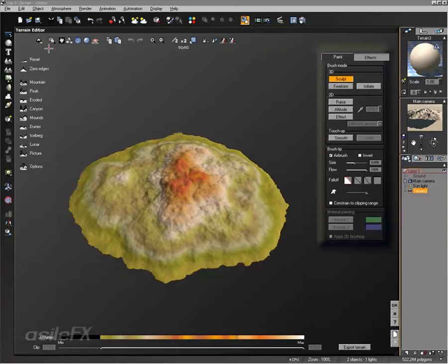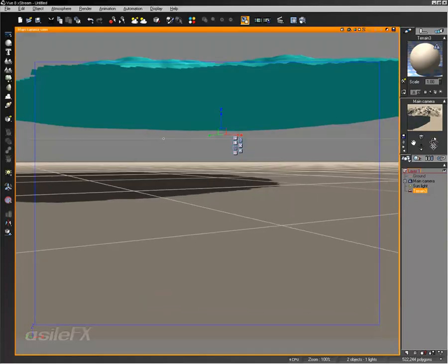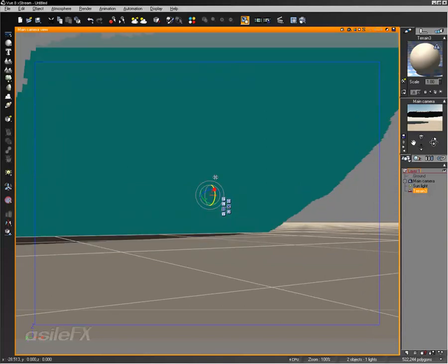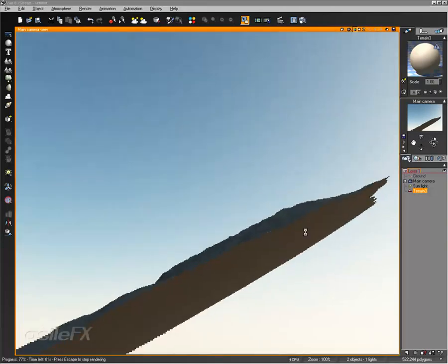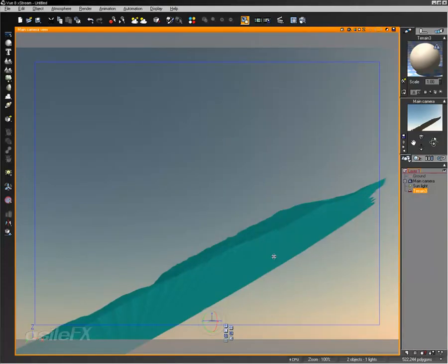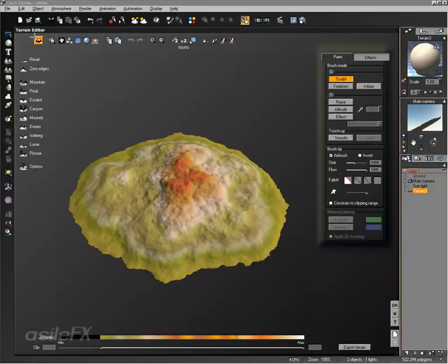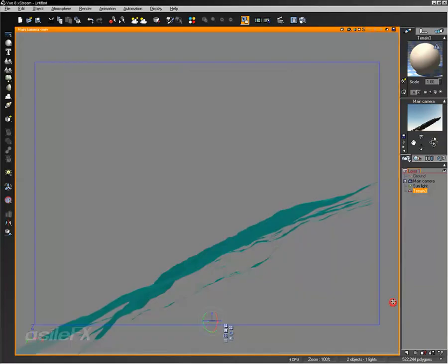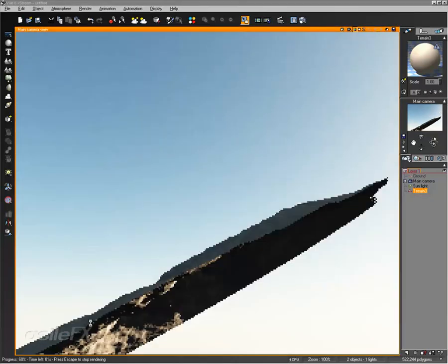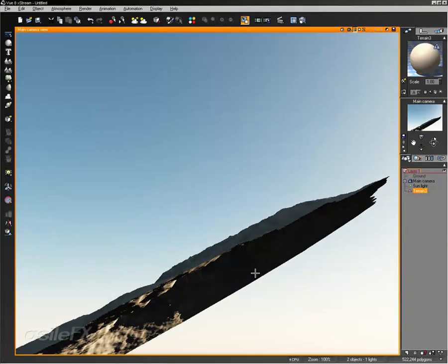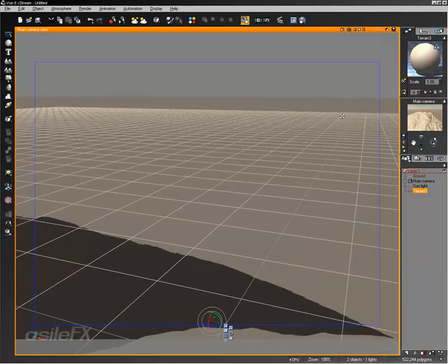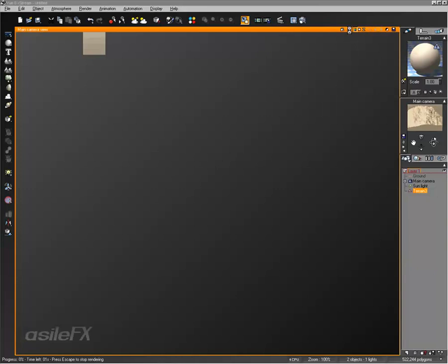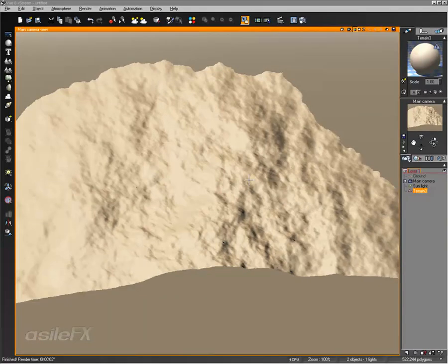If we turn off the symmetrical option and take a look at the bottom of the terrain, what we're going to see is a flat polygon. And what this is doing is kind of filling in the terrain and cutting it off, as if we were to slice a piece off. If we switch it over to the skin only and now take a look, we're going to see just the underneath of the geometry. So you could even flip over the terrain, and although we're not seeing the double-sided polygon, that geometry is there from the underneath part of the terrain.